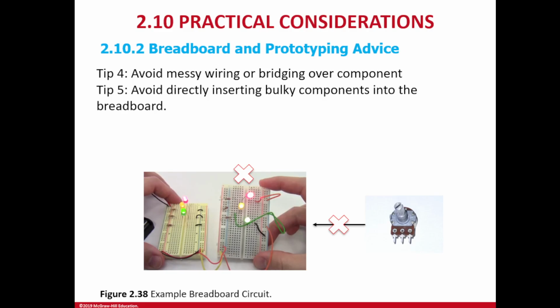Avoid directly inserting faulty components into the breadboard. For example, this is a potentiometer, and those three terminals are not very thick. Even though you can push it in, over a period of time the spring inside the breadboard will come loose.